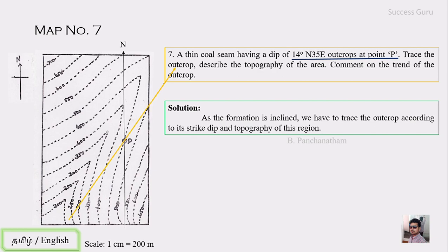So this will be the true dip direction, and we have to mention it as TD without leaving it, right? Because what happens when we are solving a map without mentioning the direction or any other details, this may lead to confusion at a later stage, right? So whenever you are plotting a true dip direction, mention it as TD and only in the direction which they have given, not in both directions.